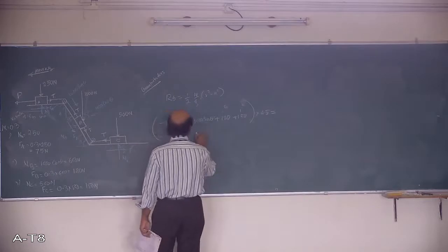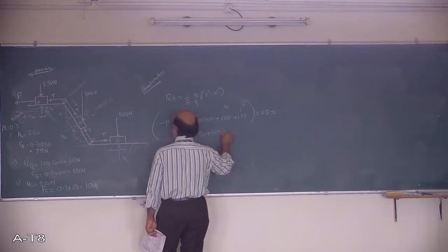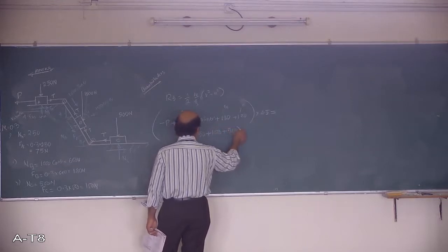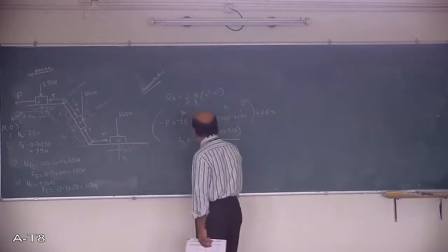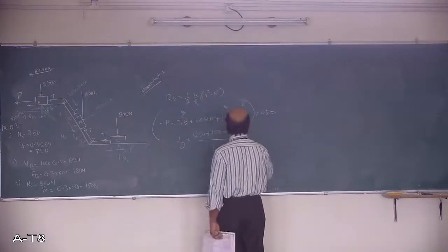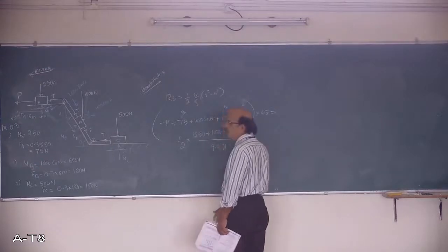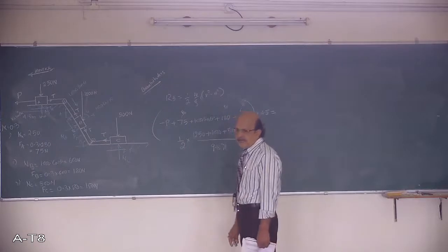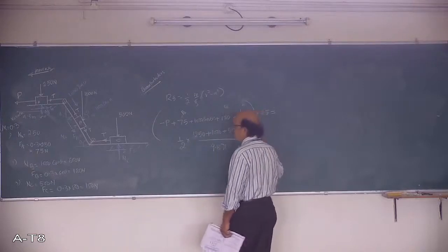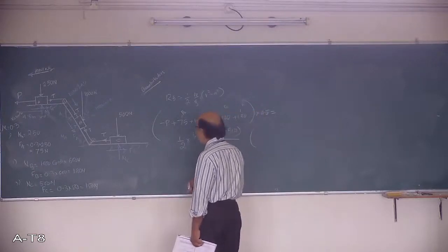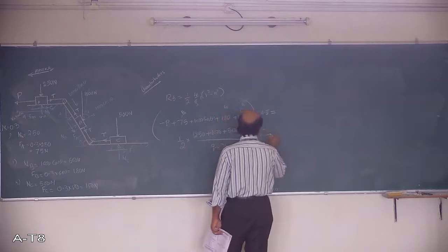That is 250 Newton, 1000 Newtons, and 500 Newton. All the three I will add here, and gravity is 9.81. You can take it. And in the bracket, as all are connected bodies, the velocity will remain the same, either initial or final. So I want to know what the final velocity is, given as 3 meters per second. Initially it starts from rest. So 3 meters per second squared minus 0 squared.